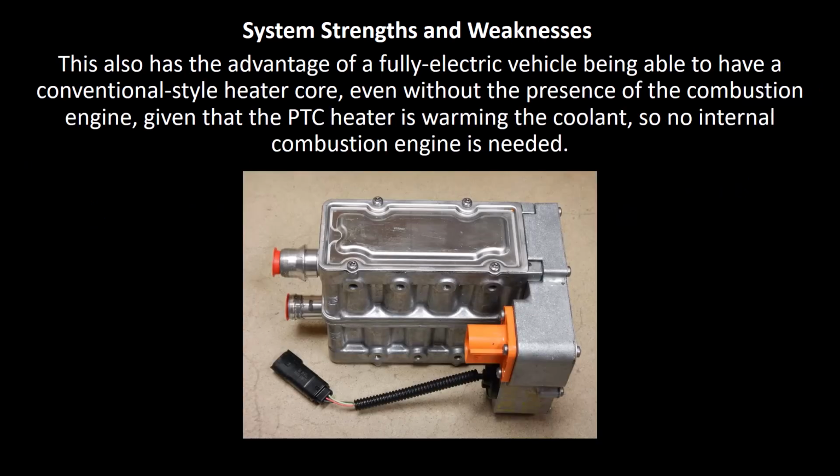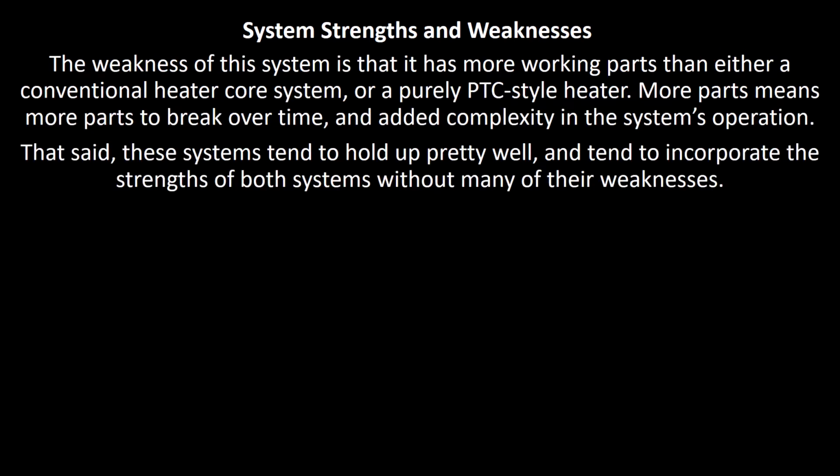This also has the advantage of a fully electric vehicle being able to have a conventional style heater core even without the presence of a combustion engine, given that the PTC heater is warming the coolant, so no internal combustion engine is needed. The weakness of this system is that it has more working parts than either a conventional heater core system or a purely PTC style heater. More parts means more parts to break over time and added complexity in the system's operation. That said, these systems do tend to hold up pretty well and tend to incorporate the strengths of both systems without many of their weaknesses.